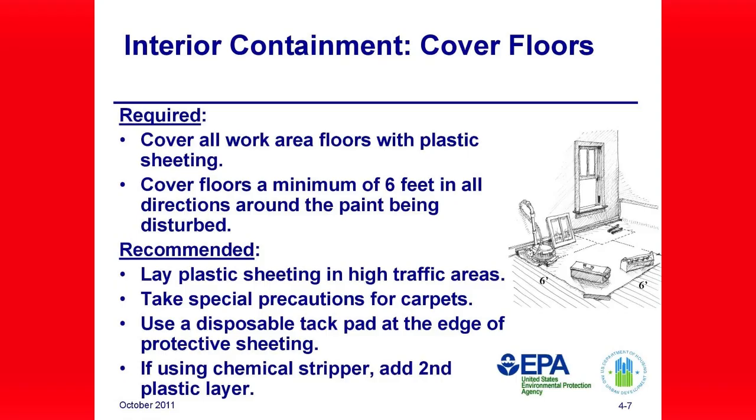If vertical containment is used, floor containment measures may stop at the edge of the vertical containment. Take special precautions with carpets in the work area. Carpets collect a lot of dust and are very difficult to clean.